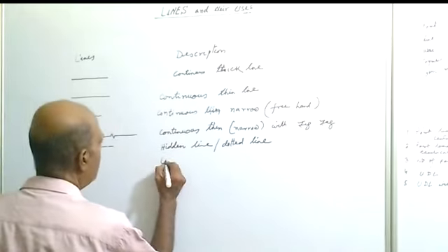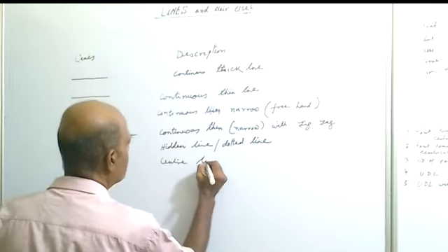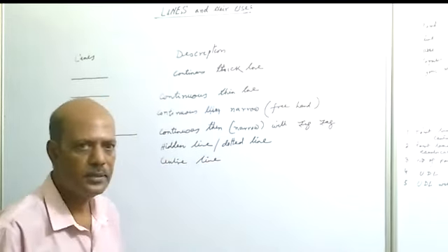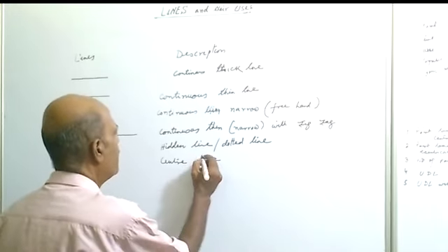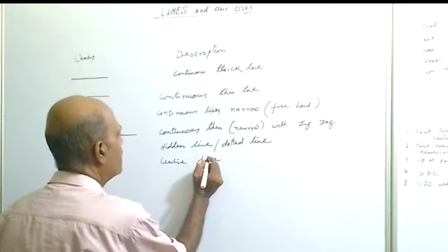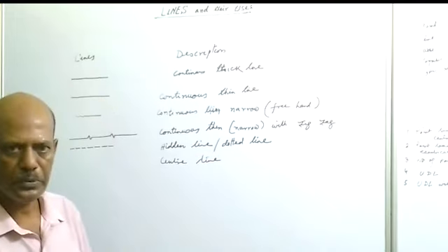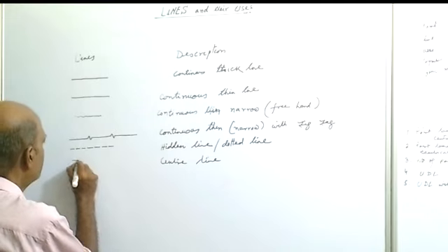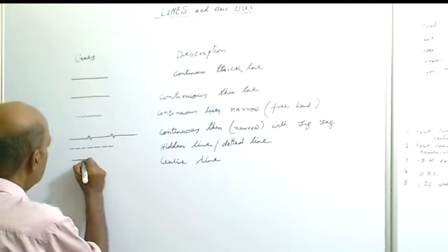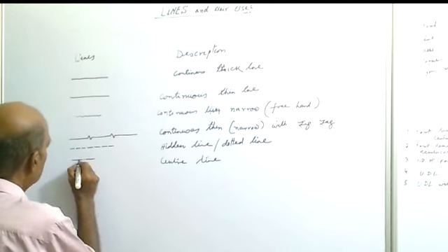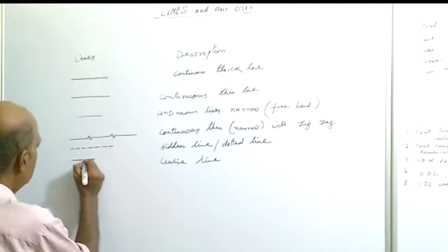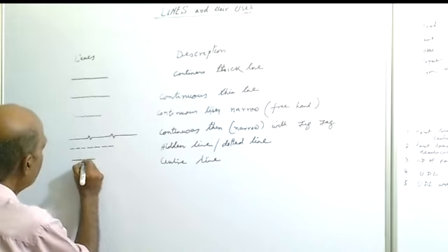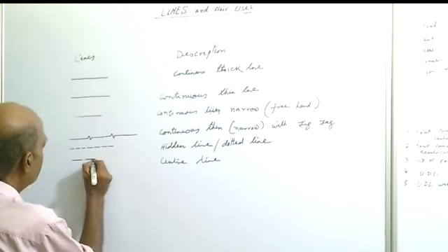Now we will see the center line. To show the center of a symmetrical object, the center line is used. It is drawn like this: just 4 to 5 millimeter or slightly more, then leave a 2 millimeter gap, put a dot, then a 2 millimeter gap, then the same length of line.